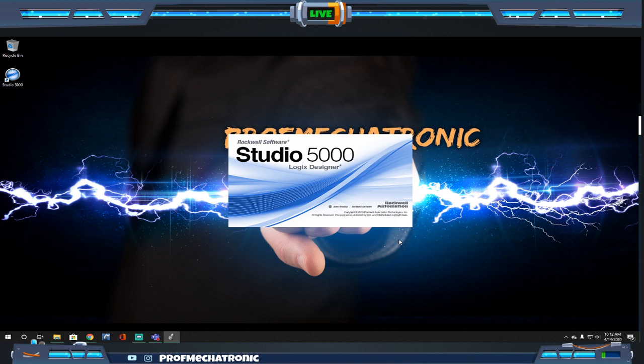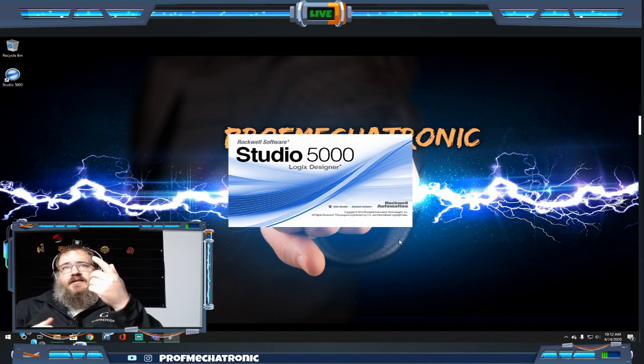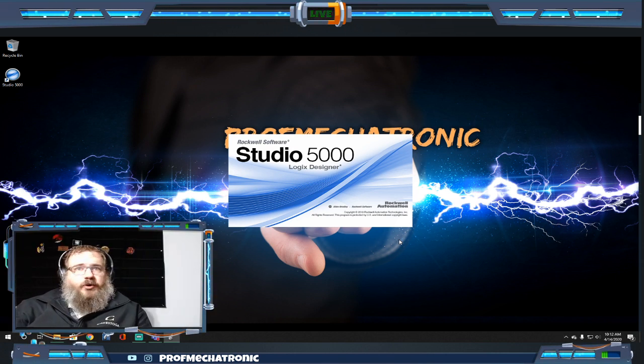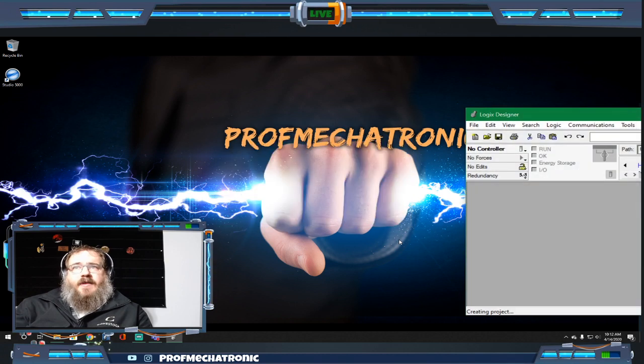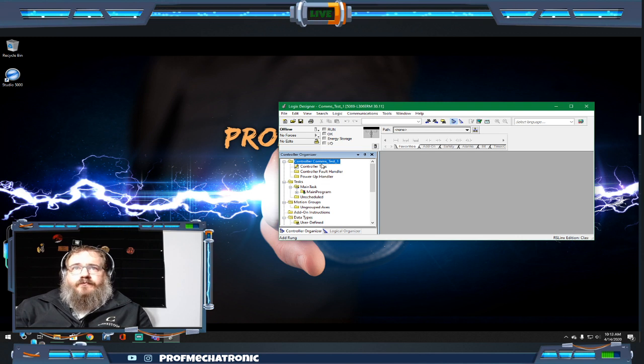Now, when you hit finish, what you're going to see is Studio 5000 is going to come up. It's going to start to build your base program for you. So your Studio 5000 base program is slowly going to start to build up. And it's going to give us, we'll move that off to the side here, our first window. We'll see it here. We got our controllers comms test 1. And we've got an entire program set up with our PLC at the bottom with the L306ERM being the processor that we have.